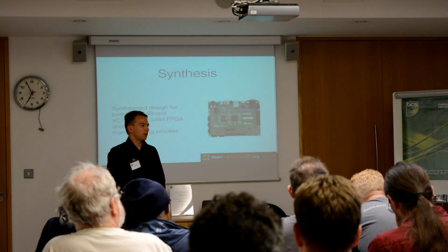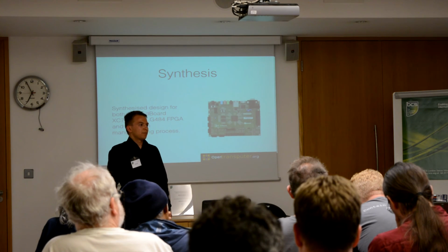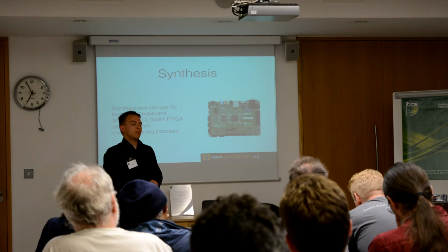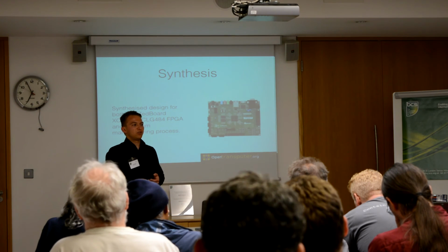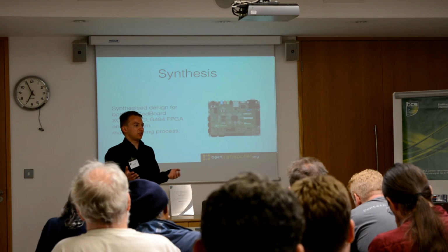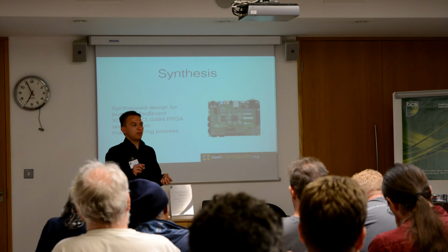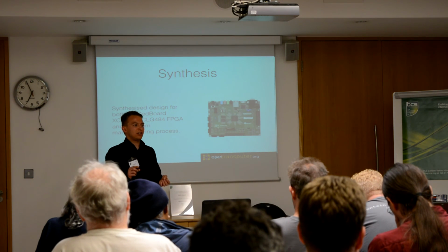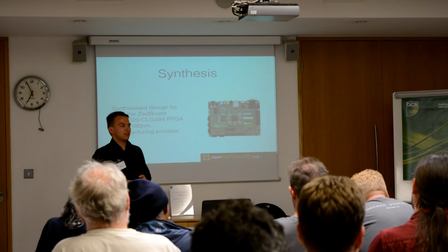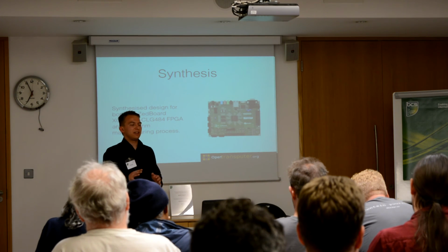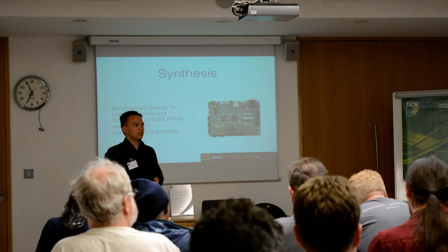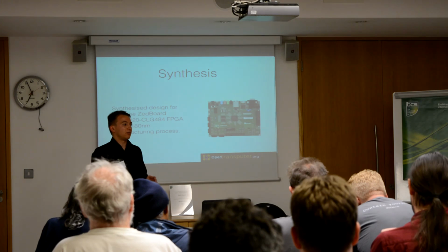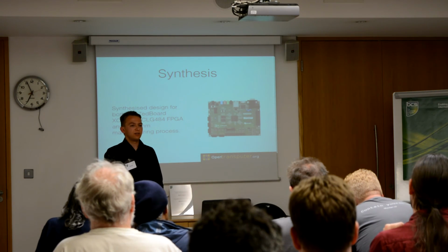Would you be able to pipeline that or kind of increase the clock speed somehow, or would that be difficult? I'm not sure if the Transputer architecture is very good at being pipelined because it's a stack machine. I think ST Microelectronics actually did try that with later generations of the Transputer, but I think it goes a bit against the idea of what a Transputer is. Yeah, we haven't experimented with this for the OpenTransputer.